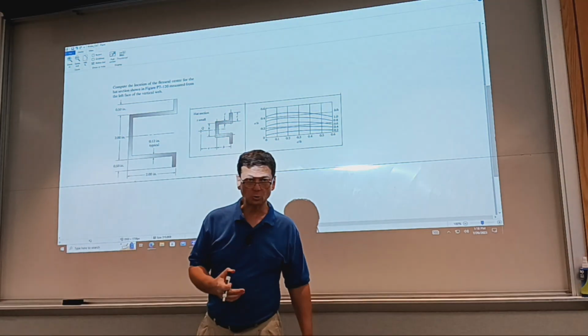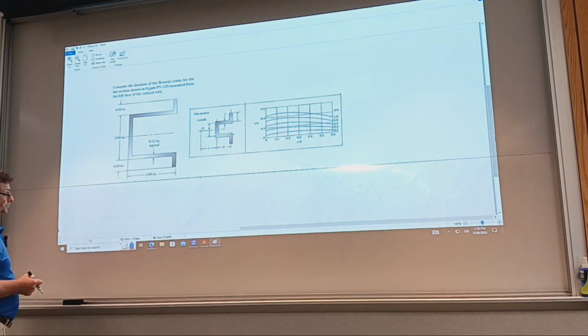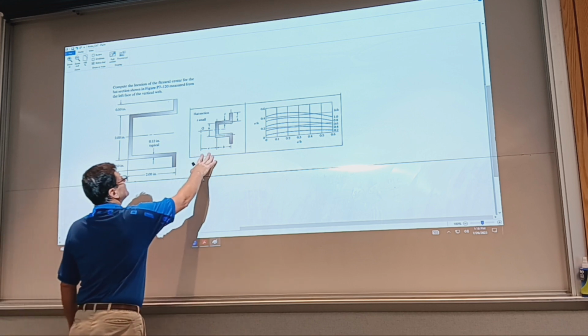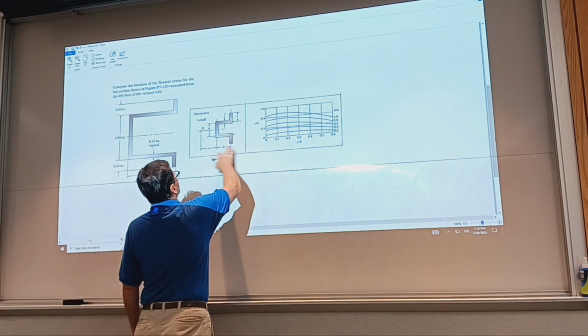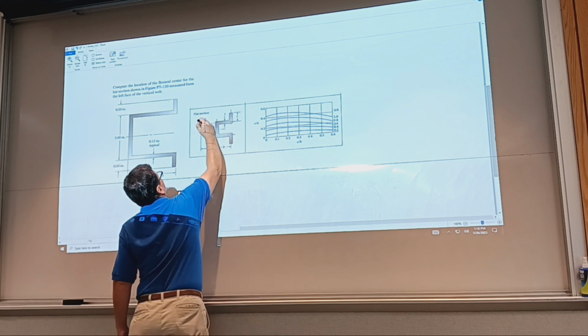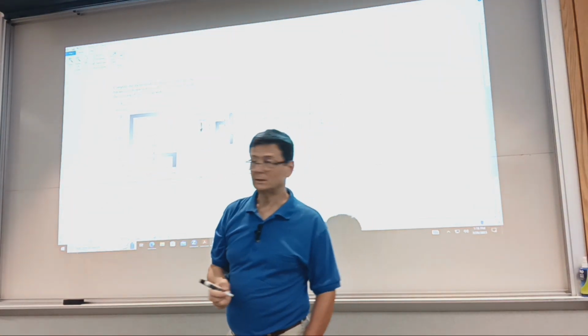And you don't want the torsion because that loads the material unnecessarily. So this is a shape for which we have a parametric chart, and it tells us where to apply the vertical load to induce only bending without any torsion.